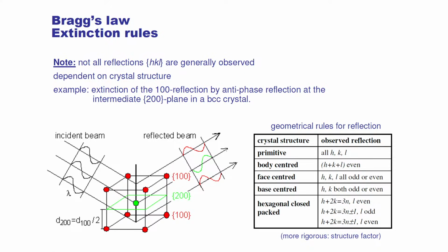If we have a 120, we won't get diffraction. So when you see pole figures, a lot of times you'll see a 200 pole figure, but you won't see a 100 pole figure, because 100 doesn't diffract in FCC, because we have an odd with 2 evens. But 200 diffracts.